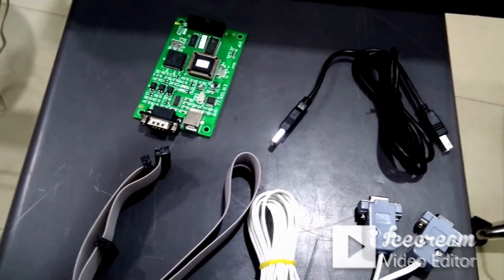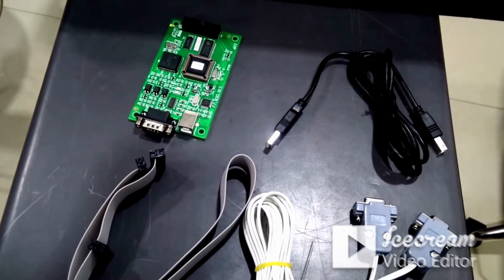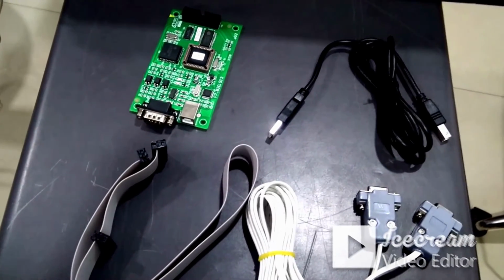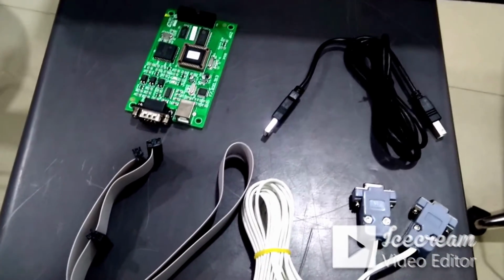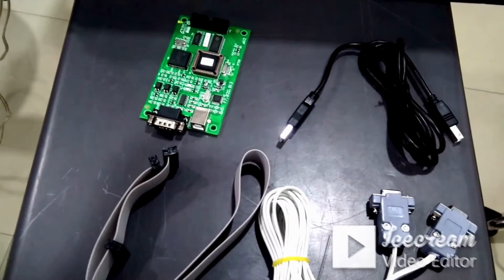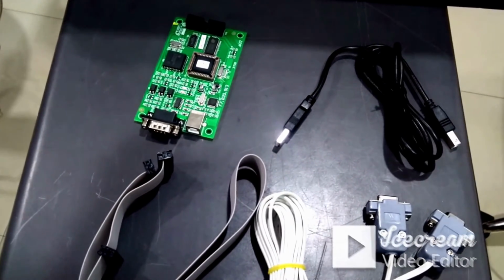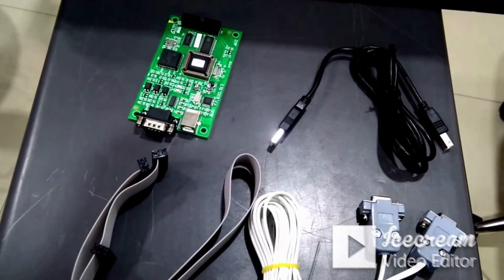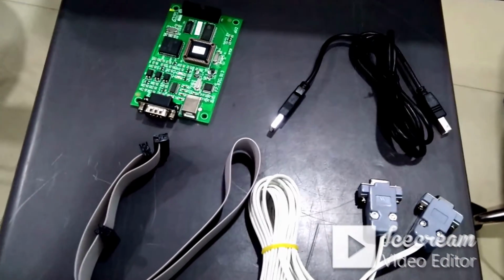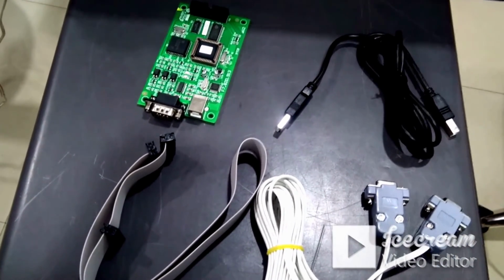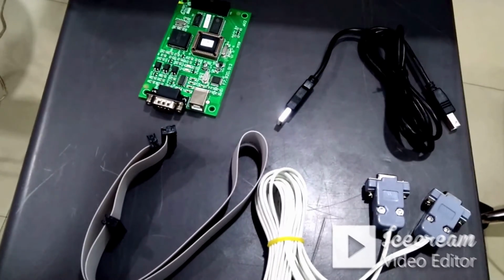We need to assign all these devices, whether this is a detector, MCB, sounder, or module, all these things we need to define using that software, and we need to create equations based on the scenario so that the sounders will get activated. So for this we need the GST Define Tool software.